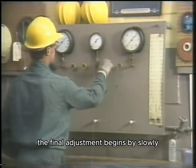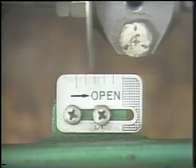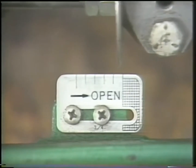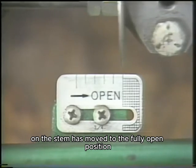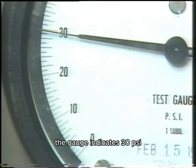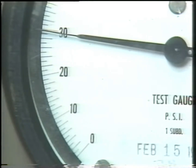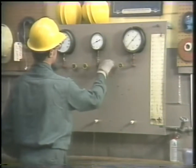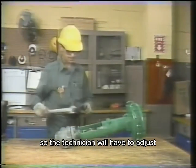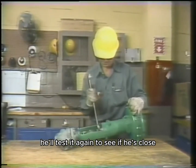The final adjustment begins by slowly applying air pressure to the actuator. As he applies the pressure, he watches the position indicator on the actuator. When the indicator on the stem has moved to the fully open position, the technician looks at the air pressure gauge again. The gauge indicates 30 psi. That's a little low. The valve should be fully open at 35 psi. So the technician will have to adjust the nut to increase spring tension. When he feels that he has tightened it sufficiently, he'll test it again to see if he's close.